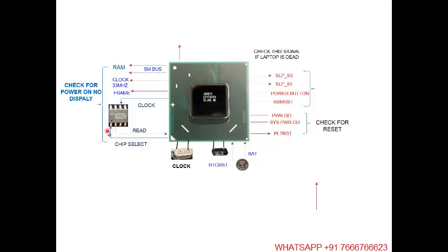Connect the oscilloscope or logic analyzer at pin number 1 and turn on the laptop. As soon as you turn on the laptop, you will find some waves, some oscillation on pin number 1. And if they are coming, that means the PCH is responding. The PCH is trying to access the BIOS.